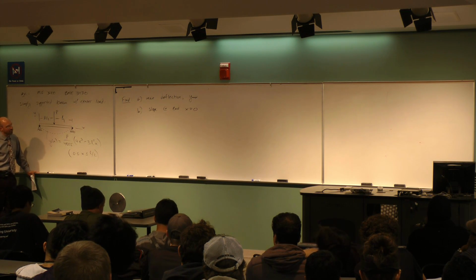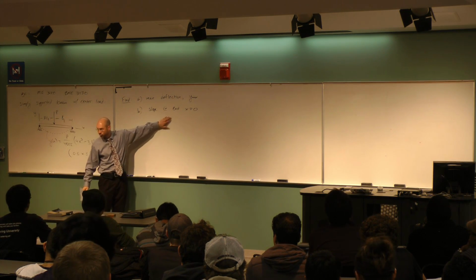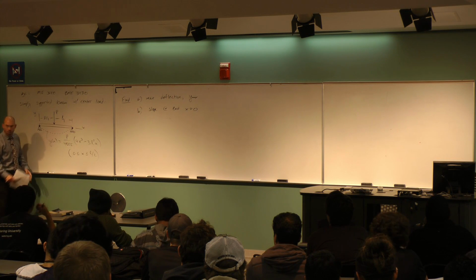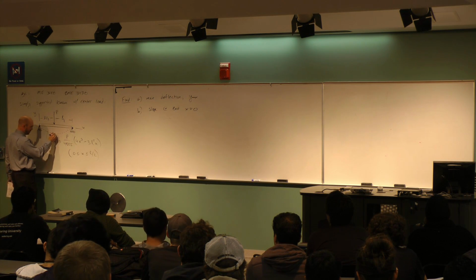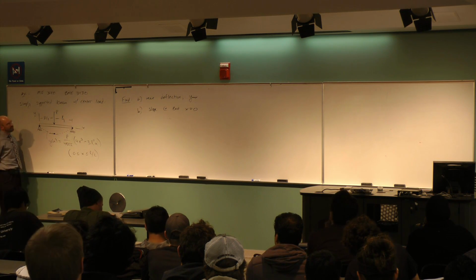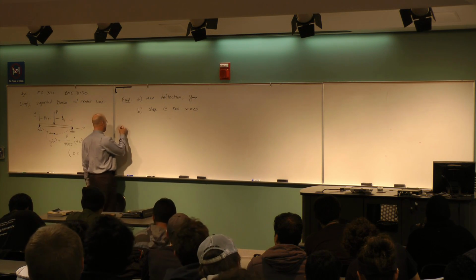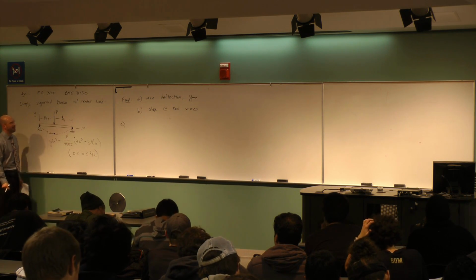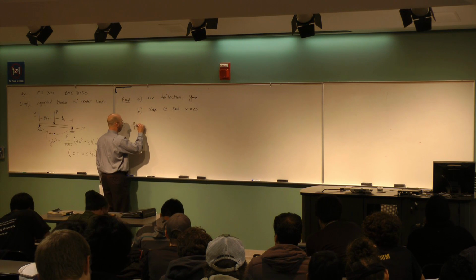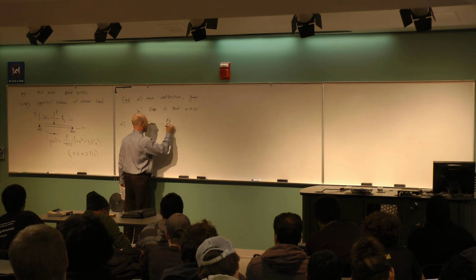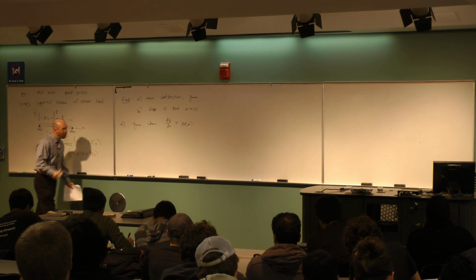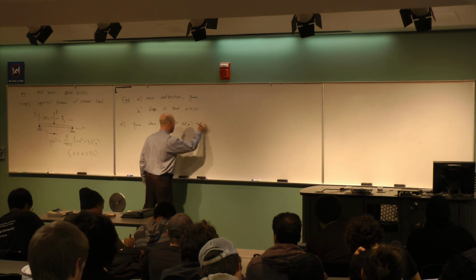But since this is an example of derivatives, and we're going to need a derivative anyway, because I want the slope, which by definition is the derivative, why don't we see whether or not calculus tells us what we think? Because if this is the maximum, then this should be a flat spot, and the slope should be equal to what? 0. So we can at least see if that'll happen. All right, so we'll go ahead and take a regular calculus approach to this, even though I can see by inspection the answer should be x equals L over 2. But y max will occur when the derivative, dy/dx, which is by definition the angle theta of x if the angle's small, is equal to 0. That'll give me the flat spot.